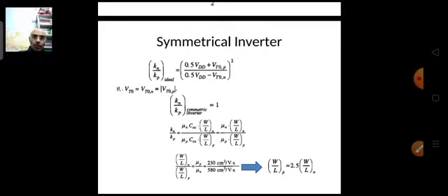So if you keep on reducing the device length, then the mobility changes, because of the velocity saturation and the other things. So the mobility itself is affected. For the long channel devices, this mobility which we have written here is for the long channel device. So for the short channel device, it will be something different.